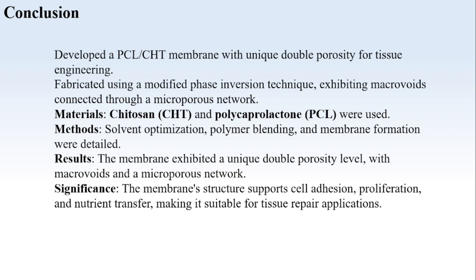XRD and DSC studies indicate increased crystallinity and melting point with higher chitosan weight percent. Biodegradability is adjustable by varying the PCL chitosan ratio, with enzymatic degradation showing selective PCL degradation. HUVEC demonstrate rapid attachment and proliferation, maintain natural morphology, suggesting potential for vascular graft application in tissue engineering.